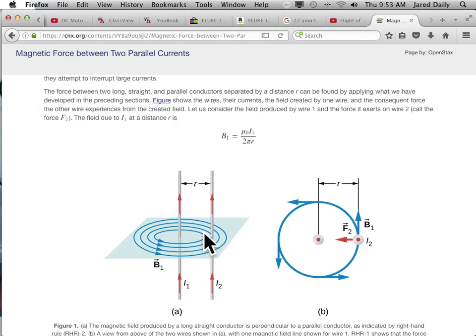And on those towers for power lines, there's currents going both directions. They have to make sure that the forces are not going to push wires towards each other ever. Or if they do, that there's not enough slack in the lines and there's enough distance between the lines that they'll ever touch, right? You don't ever want the wires to touch no matter which way the currents are going. So they separate the wires and they allow enough slack.